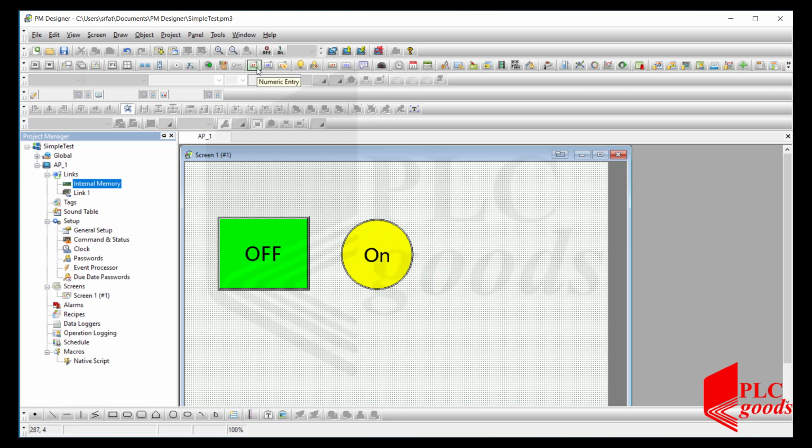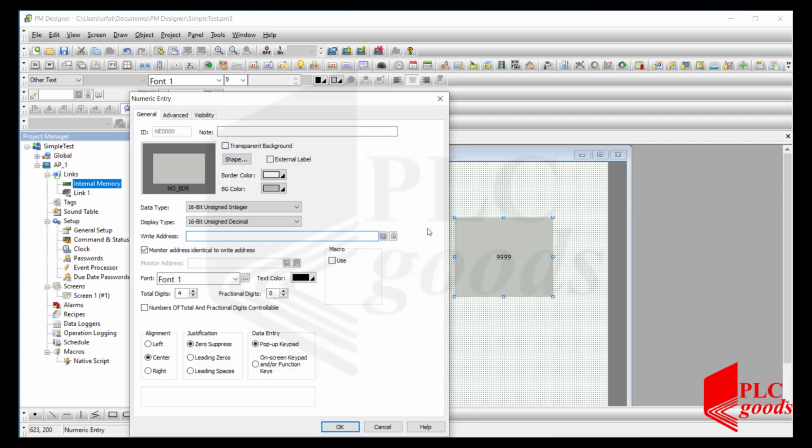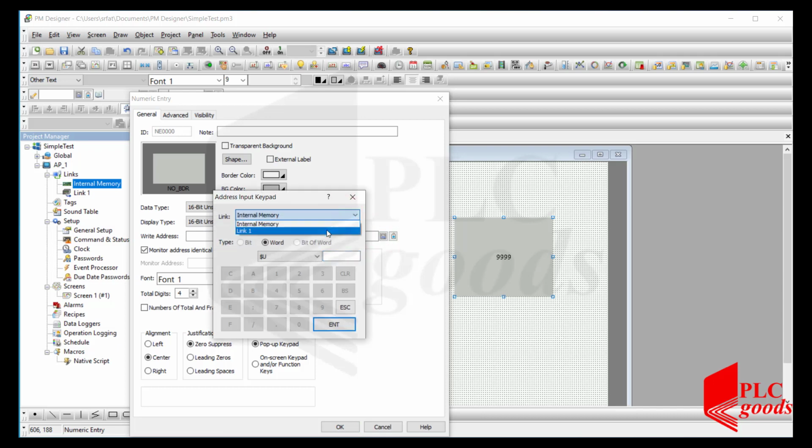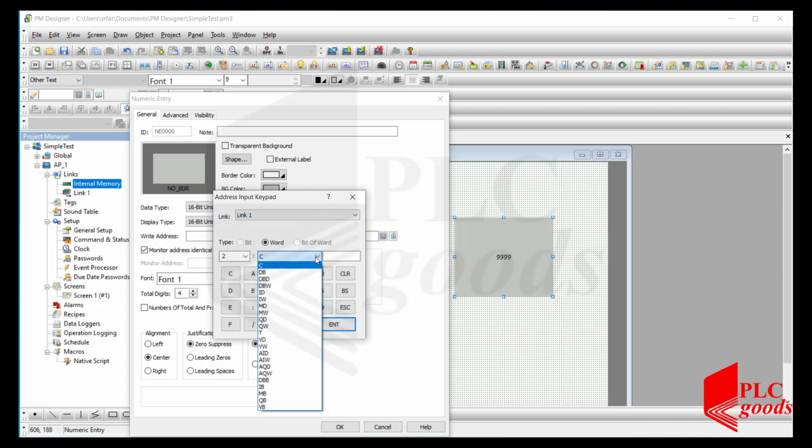Well, to test the created link between my HMI and PLC, let me use a numeric display and then connect it to MW30 of my S7-300 PLC through the created link. Remember, MW30 indicates the cabin's position.